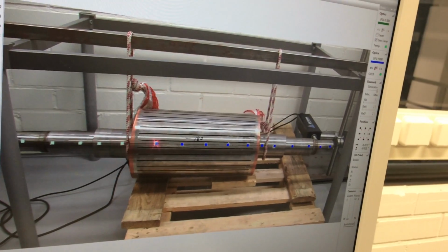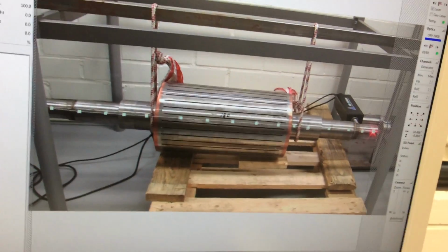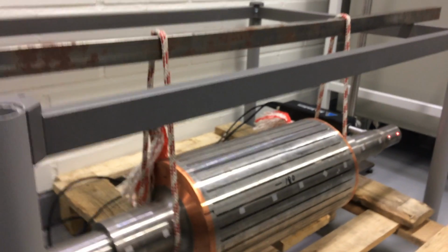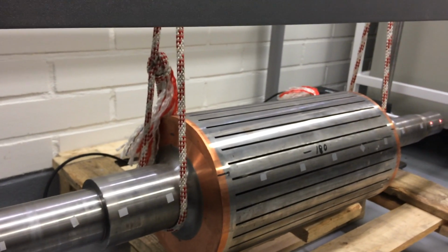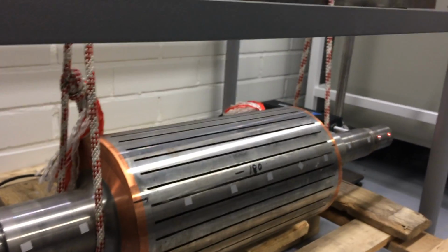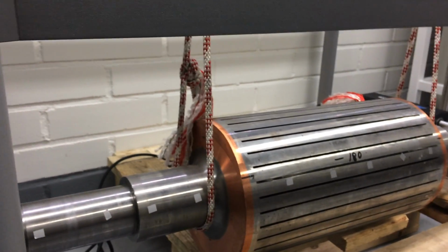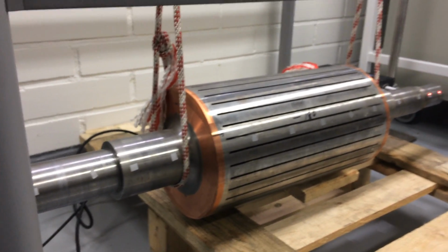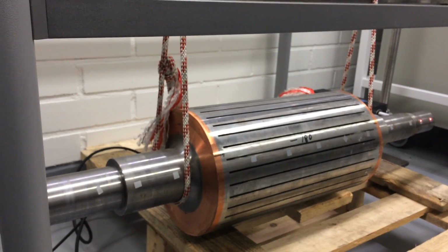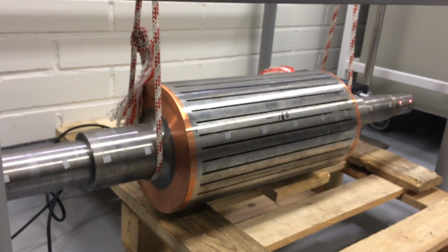The next part focuses on these points. But if I go back to the rotor, I will show you that I actually put some reflector tapes. You can see those points. I just glued them to the shaft. The reason is the surface of this rotor is quite shiny, and it's not so good for a laser head to receive the maximum reflection. So that's why I put those tapes.